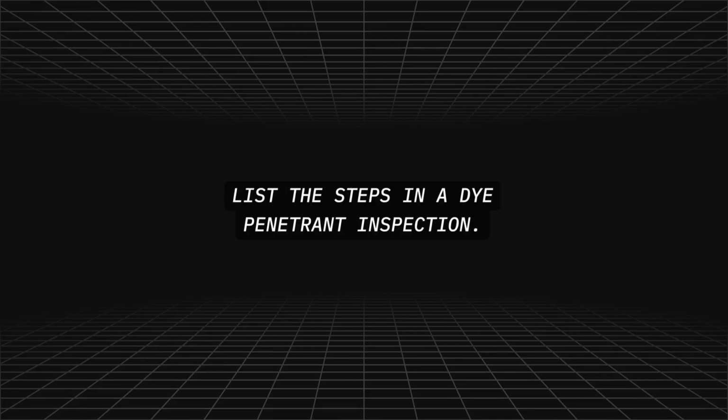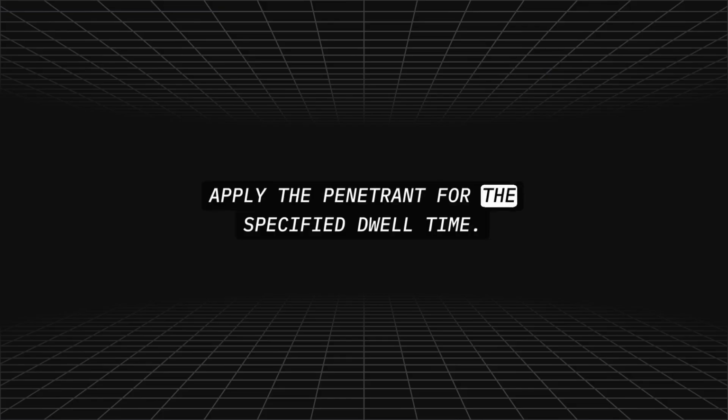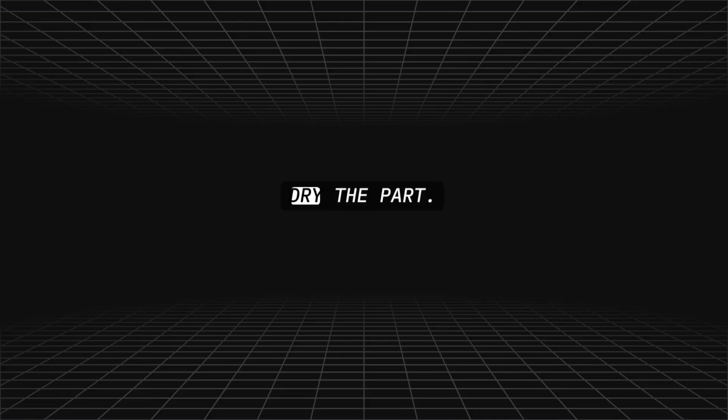List the steps in a dye-penetrant inspection. One, thoroughly clean the material's surface. Two, apply the penetrant for the specified dwell time. Three, remove the penetrant with water or emulsifying cleaner. Four, dry the part. Five, apply the developer. Six, inspect the results.